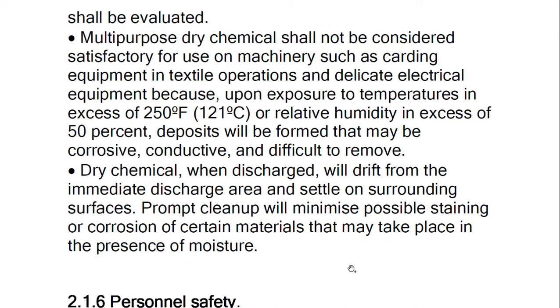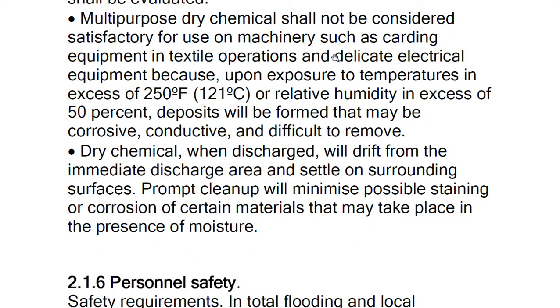Multi-purpose dry chemicals shall not be considered satisfactory for use on machinery such as carding equipment in textile operations and delicate electrical equipment, because upon exposure to temperature in excess, or relative humidity exceeding 50%, deposits will form that may be corrosive. So whenever powder remains, the residue is in fact corrosive in nature. Dry chemical when discharged will drift from the immediate discharge area and settle on surrounding surfaces. Prompt cleanup will minimize possible staining or corrosion of certain materials that may take place in the presence of moisture.